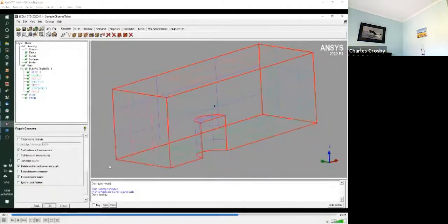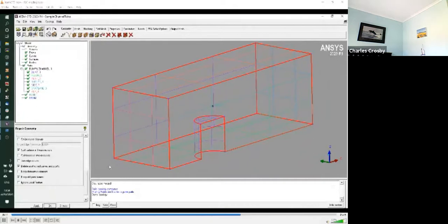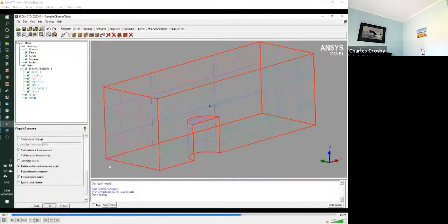By definition, for an unstructured mesh, an edge forms a boundary between exactly two faces. Think about this for a moment. If there was only one face adjacent to an edge, it would be open. If there were 3 faces coming together at a single edge, that would leave you with a 0 thickness surface.